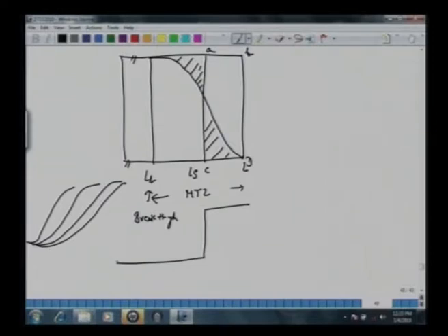Another way of explaining that: if everything is ideal, or there are no dispersions, or all kinetics are fast here, all rates are fast, pore diffusion, mass transfer coefficient, interface mass transfer, and everything is decided by the rate of adsorption and desorption, one would expect the front to go like this.